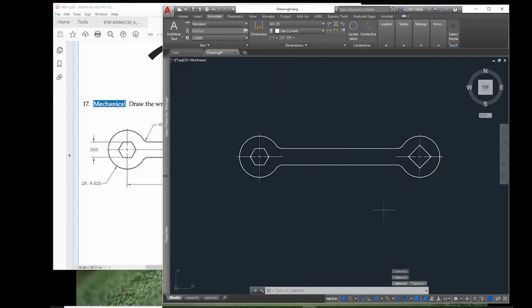Cool. Now let's put in that center line, which is also under the Annotate tab, right next door to the center mark. This tool will place a line exactly between two other lines, so I'll click on this top and bottom line, and boom, there it is.